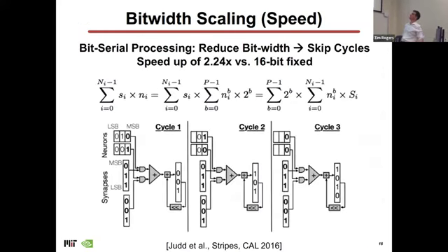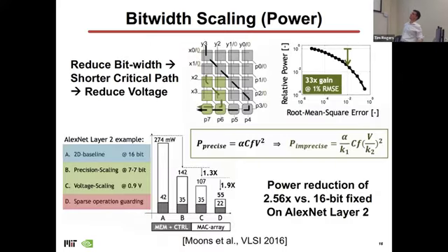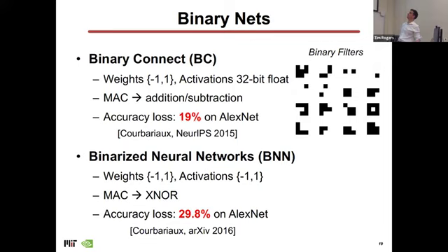Right, okay, so this is just sort of the precisions you need. Bit width scaling, yeah, so these are just a bunch of different academic works that have also tried to take advantage of shrinking bits, et cetera. Binary neural nets: why do I need any more than one bit, right? I mean, that's next. That's where we're at. Come take this class in 2 years and that's where we'll be. But right now it sucks, right? Accuracy lost 19% on AlexNet; they can't get the training right on that lower precision at this point, or at least at the point of these slides.